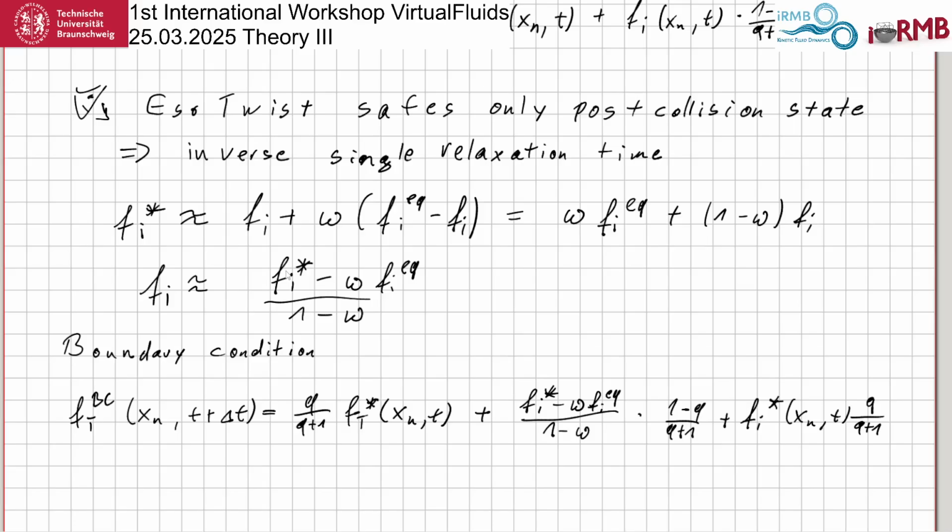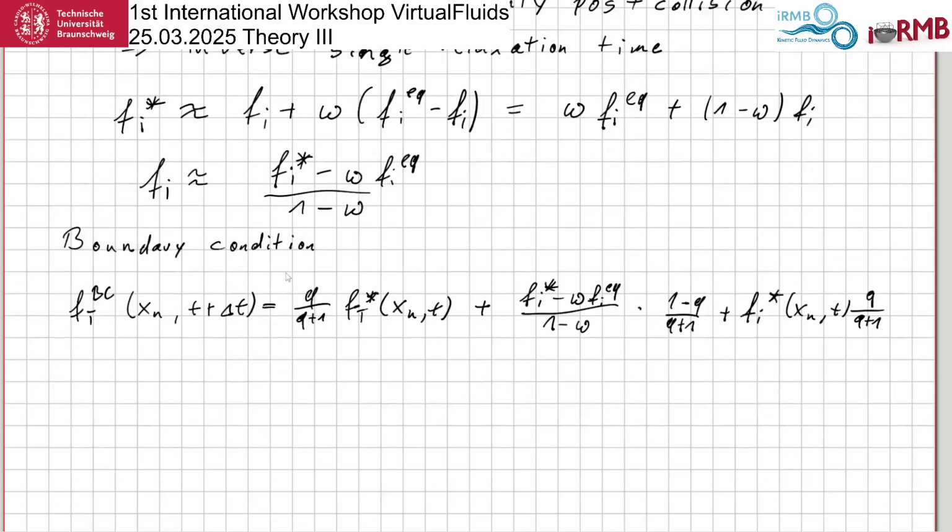But one thing is how to compute it. Another thing is, if you have something like an aerodynamic shape, a wind turbine blade, then the boundary layer is extremely thin and very important. Therefore, the only way you can get around it is resolving it. So this is why the next point here is grid refinement. Maybe I'll just go on and say grid refinement.